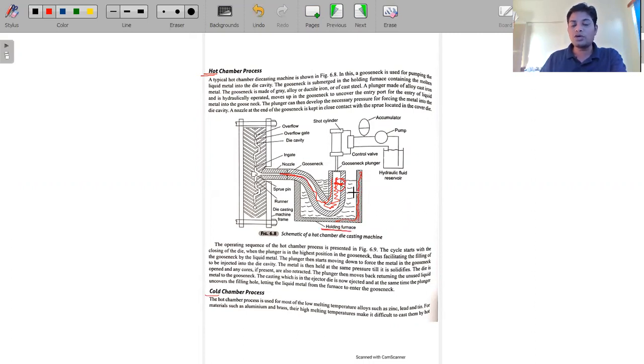Okay, in which you are melting the material, and through some mechanism we are just pumping it inside this liquid material. This molten material we are pumping it inside, and once some volume of the molten material is filled up to this, then what we are doing is we are just pushing it inside. So this is basically the gooseneck, some kind of plunger we are using.